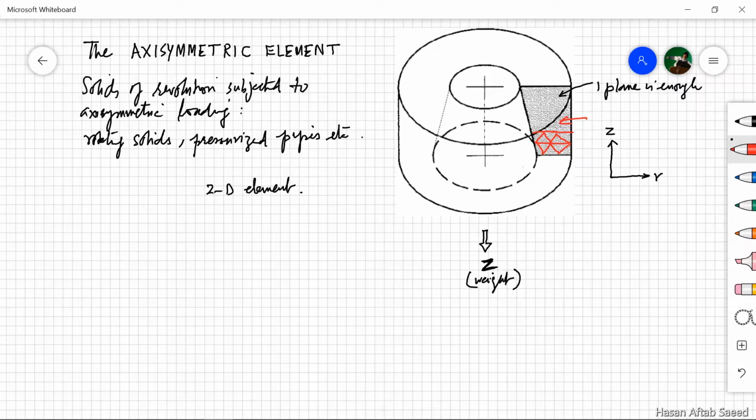Now, another body force, which is very common, will be applied because of centrifugal force. If this revolves, then it will be in this direction. And obviously, this is not to say that it is in the positive r direction only; it is in every direction, because any plane of this body subjected to this kind of loading is experiencing exactly the same thing. Now, when it comes to pressures, there would be a pressure in the radial direction.